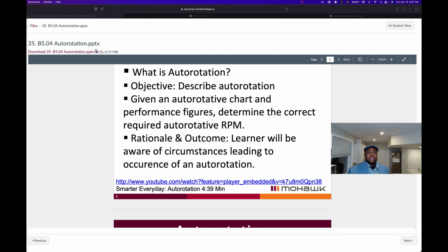Several factors affect autorotation. We can think about airspeed, density altitude, weight, and rotor RPM. Density altitude refers to how dense the air is relative to what altitude we would typically find that type of air. A low density altitude is air that is typically found at lower altitudes, which is better for aerodynamic performance.